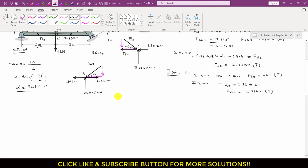Now at joint A, if we apply the summation of forces along y equals to 0, as we can see that this is acting in the positive direction, so I will write plus 0.875, and this component is acting in the negative direction, and it is the sine component, so I will write minus FAD sine of alpha, and alpha is 36.87, and this is equal to 0.